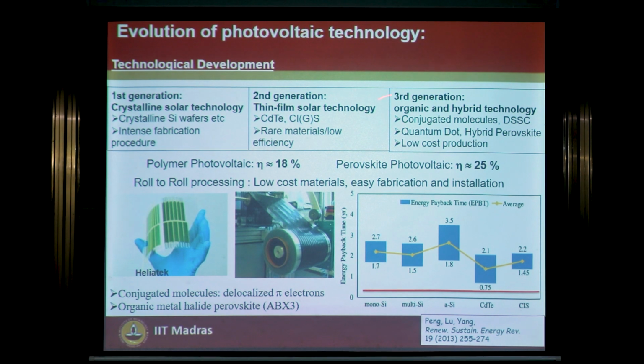So in all this third generation system, as I mentioned, it's not only the low cost of the molecule, it's also that the production process itself is pretty low cost. One can envisage that it can be made with an A4 size printer, putting in a proper kind of ink, and ink basically means the photoactive materials and also some buffer layers, where one can basically print your solar cells and put them out on the rooftop. That's a very forefront thought, but currently at laboratory scale one can do roll-to-roll processing of these solar cells, and that's an important point to sell it.